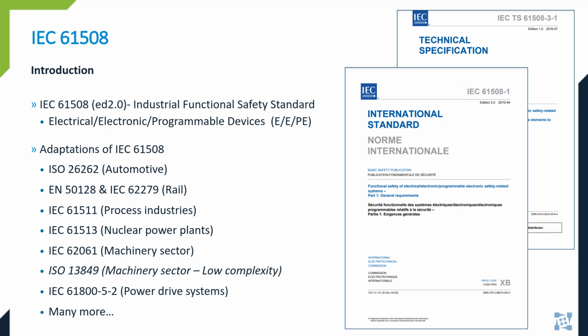Now, 61508 has two fundamental principles that must be followed. The first one is following a safety engineering lifecycle process, and it's defined based on best practices. So many highly experienced engineers from various companies authored this standard, so it contains a wealth of knowledge. The second principle is based on using a probabilistic failure approach to measure and account for the safety impact of device failure. There is something called a safety integrity level and a class level, and I'll be covering these two principles later in greater detail.